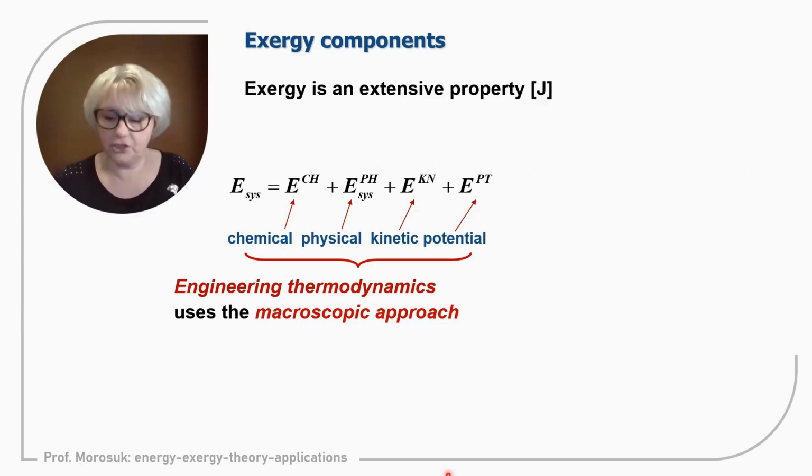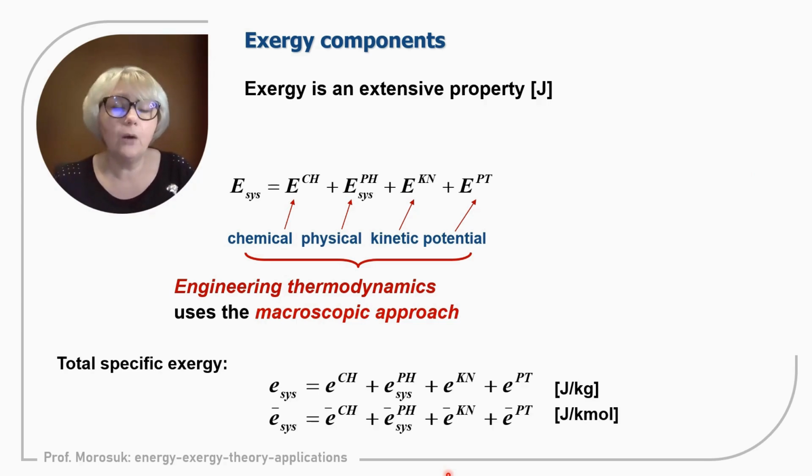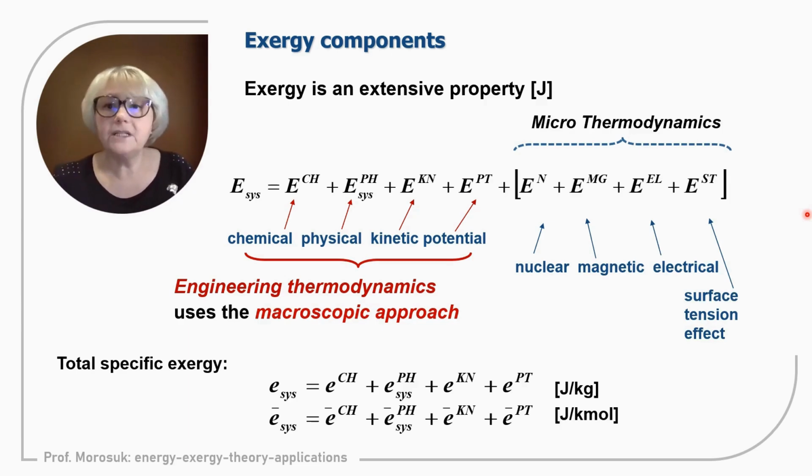And since exergy it is extensive property, we can calculate specific exergy, of course, on the mass base or on molar base. Volume base is not very popular in exergy analysis, but also volume base is possible because exergy, I will repeat, it is extensive. For scientists who are working with microthermodynamics, with statistical thermodynamics, exergy analysis is also possible to apply. Then we need to calculate additional terms of exergy. It is nuclear exergy, magnetic exergy, electrical exergy, and surface tension effect, exergy of this effect.